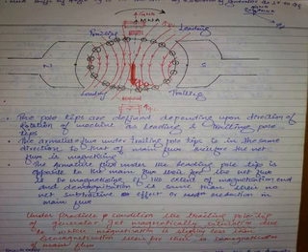What will be the flux path now? Is it the same path like that? Just imagine, will the flux flow like this only? There is opposition here, there is opposition here. So what will be the flux path in the machine now with the presence of armature flux? It will cross-magnetize like this. If you are asked, what is demagnetization in this particular case? We can expect demagnetization only due to saturation of the pole. Only due to saturation of the pole there will be a slight demagnetization, only that.